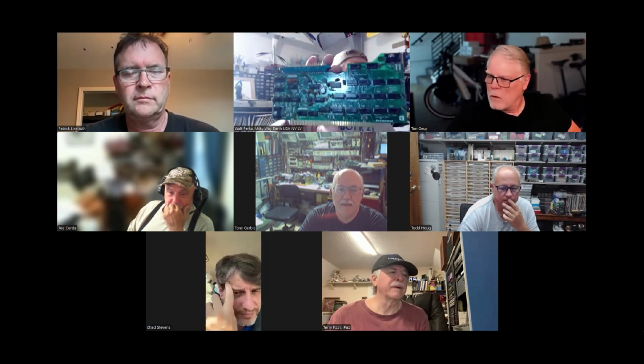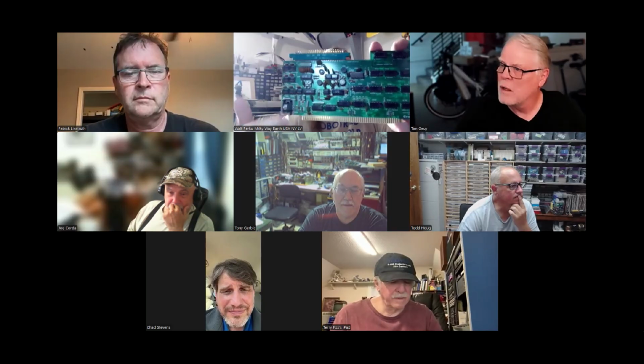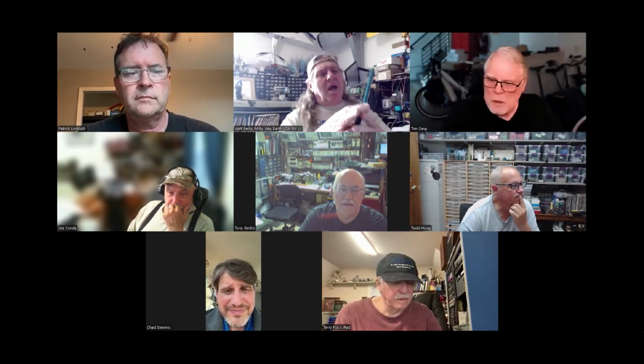There's a resistor pack on there. Let's see. There's a lot of components connected to this connector. I mean, pots, and this resistor pack goes into that connector. You can probably infer what the voltage range is from the wiring, the signals and so on, but you're going to have to actually get a joystick and actually move it around and see what the voltage range really is.